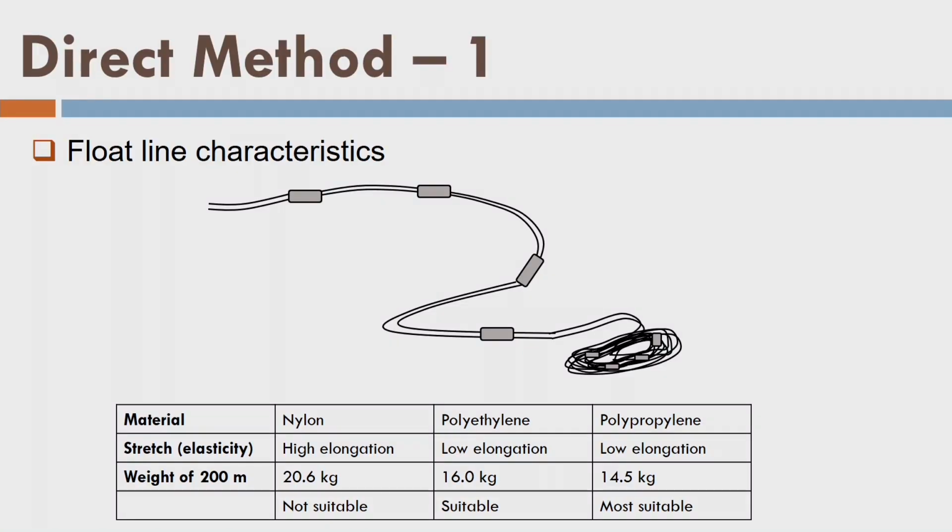remember, we have marked 3 reference marks. So at one of the reference marks, where I am putting this optical square, there itself we make a peg, or we make some kind of knot here, and with the help of some nail, we take the float line shown here on the screen, which is a graduated line, and it is having buoys. We stretch the float line across the river.